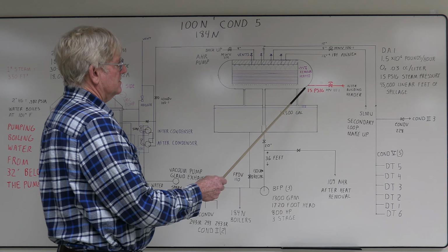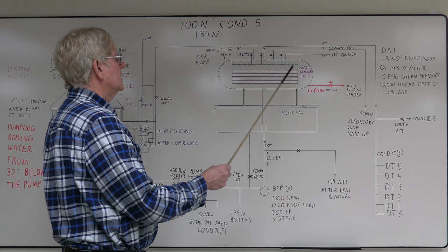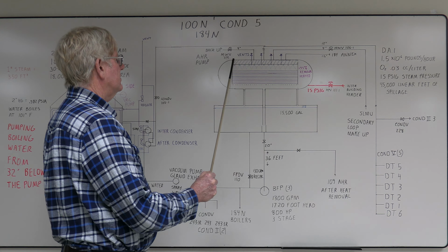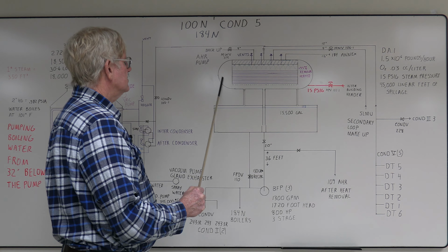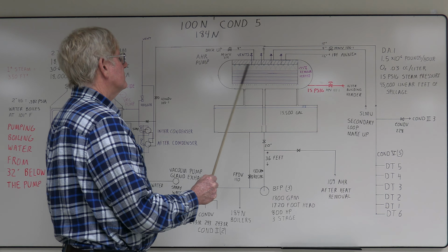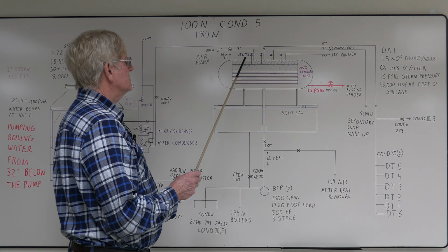So the steam was brought in at 15 psig, coming off the inner building header. So the steam would be all around here. This was actually a stainless steel box the deaerator part sat in. So the steam would come up through the bottom, through the trays, through the spray nozzles. Then any non-condensable gases were vented out. I believe these had an orifice in them too, and also a valve, probably a bypass valve too for startup.